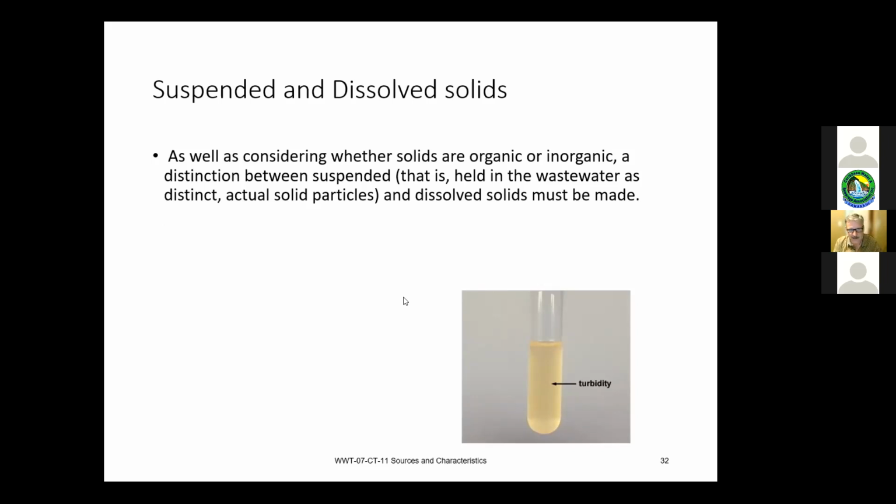So, suspended solids and dissolved solids. That's the best way to explain this. I'll just read this actually. As well as considering whether solids are organic or inorganic, the distinction between suspended, that is held in wastewater as a distinct actual solid particle, or dissolved solids needs to be made. So suspended solids are basically, if you were looking at something, you could say, okay, yeah, there are particles there, fine particles, and that would be suspended.